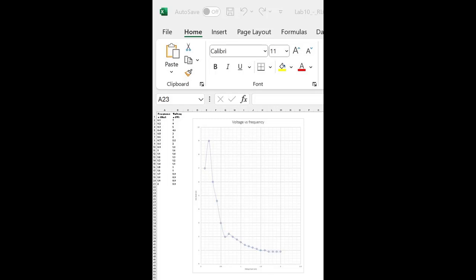Find the peak and project its location down onto the frequency axis. It might be easier to do this if you click on your graph and choose Chart Design. Under Chart Styles, you may find some of those that will put grid lines on your graph. Knowing which block holds the frequency below the peak can help you to better identify the value of the peak frequency. The write-up gives the formula for the peak frequency for a given capacitance and inductance value, allowing you to get a percentage error between the graph value and that theoretical value.